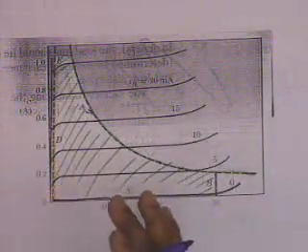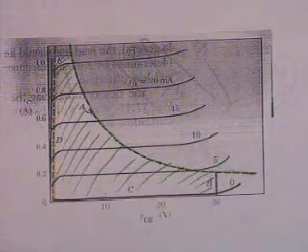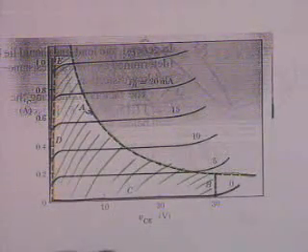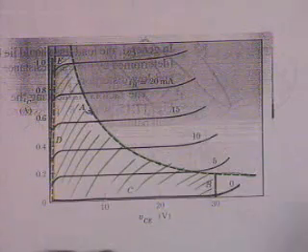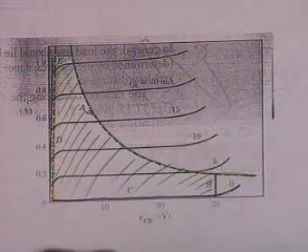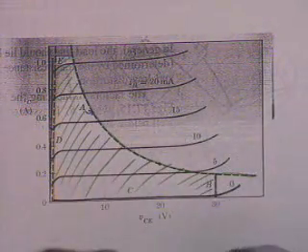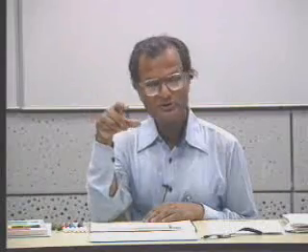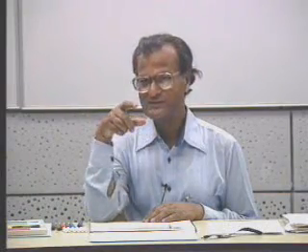Now there are other fences in this consideration, and one of them is the maximum voltage between the collector and the emitter. You know that the collector base junction is reverse biased, and therefore if you go on increasing VCB, which also increases VCE, am I making sense?